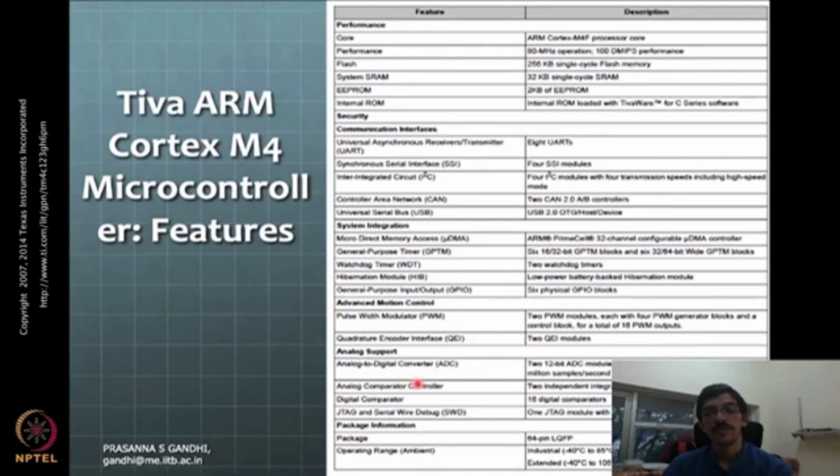So that phase difference is what gives you the direction also. So that's how this entire thing works: how to read these pulses and convert them into a count, and increment the count if the direction is positive, and decrement the count if the direction is negative. Everything is done by this dedicated interface.